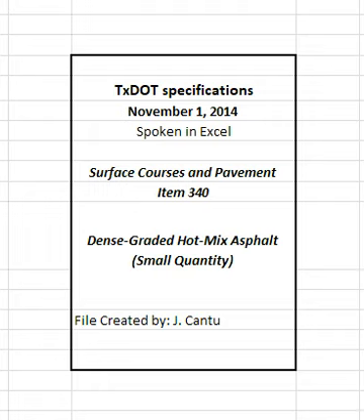4.9.5 Irregularities. Identify and correct irregularities including segregation, rutting, raveling, flushing, fat spots, mat slippage, irregular color, irregular texture, roller marks, tears, gouges, streaks, uncoated aggregate particles, or broken aggregate particles. The engineer may also identify irregularities, and in such cases, the engineer will promptly notify the contractor.